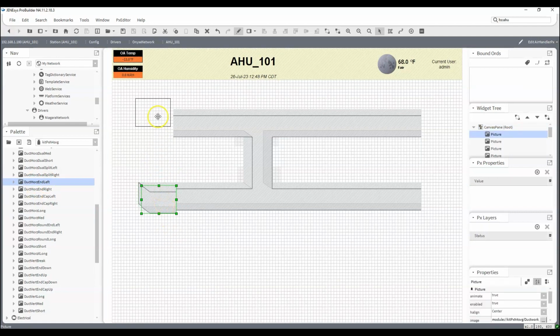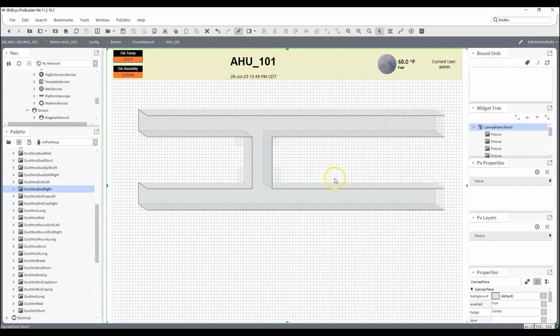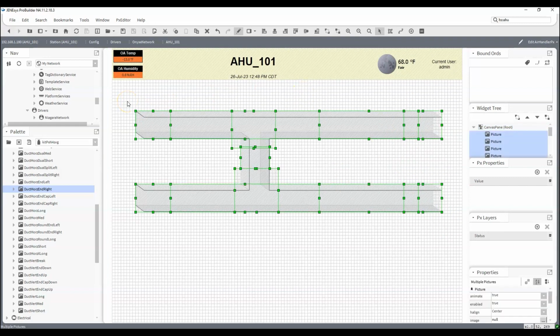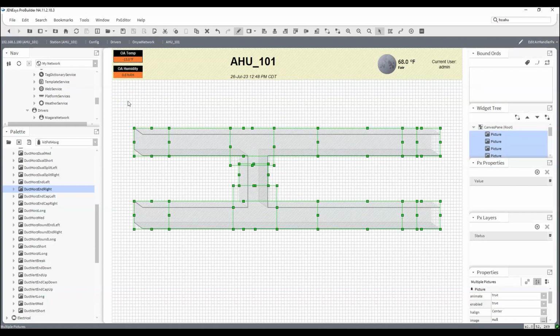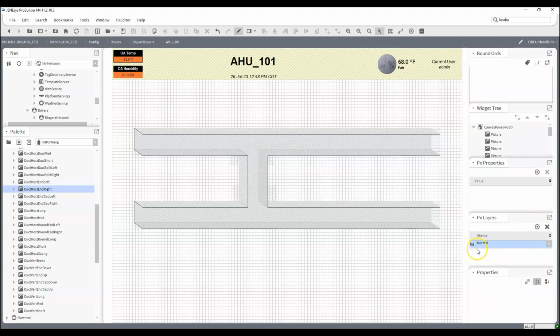So go ahead and duplicate these. And then add the right. Duplicate. Okay. Now I'm going to go ahead and select all these and get them in an area where I want. And now what I'm going to do is before I do anything else, I'm going to go ahead and add a layer, and I'm going to name this BG. And now I'm going to make this BG locked, which means that any layer that I make a BG, it's going to go ahead and lock it to the position in the PX file or in the PX page, and I don't have to worry about it moving.